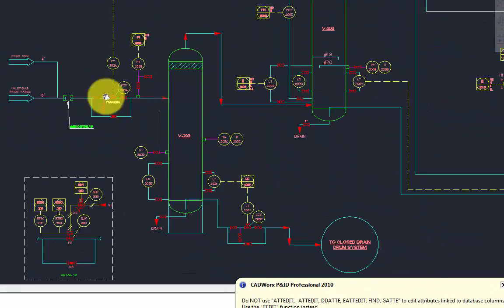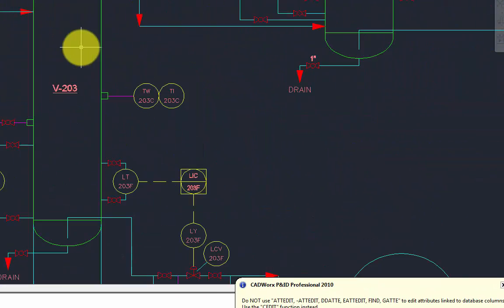So essentially, that's how we would do that with equipment, lines, valves, instruments, all of that, huh? Yes, it's pretty much the same process for each type of component. You would add X data for that certain component type into your database. And once you do one certain block type, it goes project wide. So if I had 20 control valves on here under that same name for that AutoCAD block, that map would go across the board.